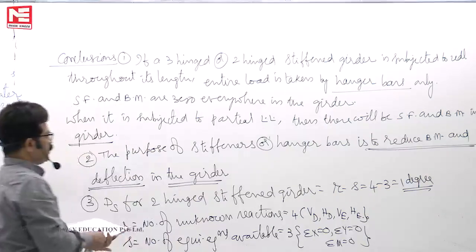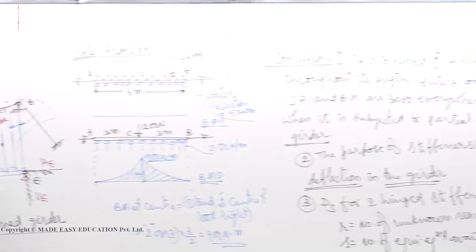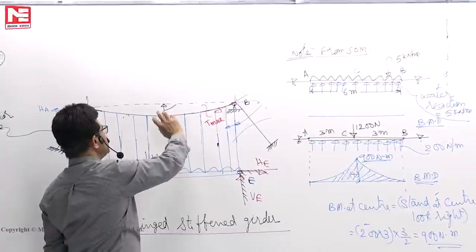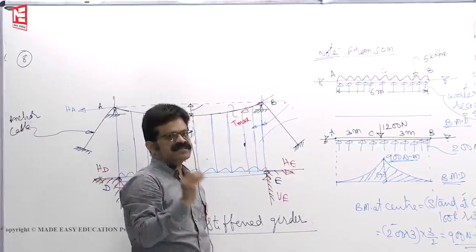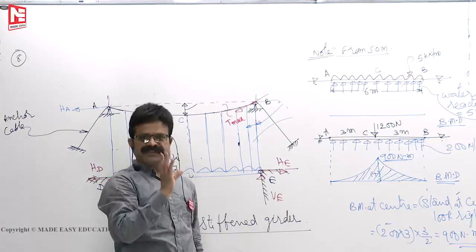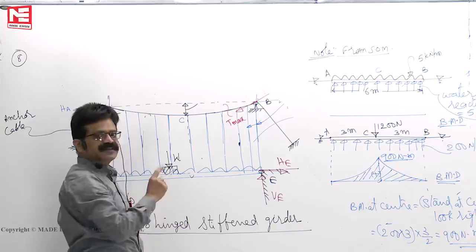Now, these are the points in this one. Now the cable takes the parabola shape. Whether you build it with concrete or steel, if it takes the shape of a parabola, bending moment will be 0. If it is below the reference line, it is subjected to tension.